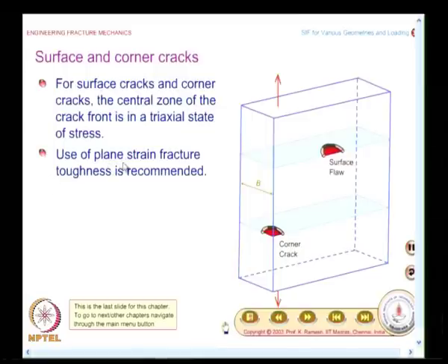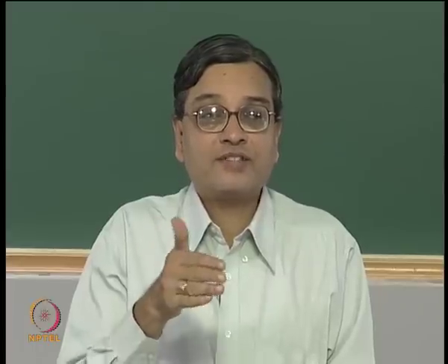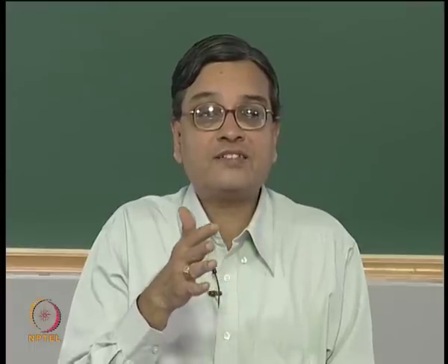And when you have to use plane strain fracture toughness, you have to recognize that surface flaws are always dangerous, because you are always comparing the stress intensity factor of a surface flaw with a through the thickness edge crack. But for an edge crack in a reasonably thin plate you may use a plane stress fracture toughness, but if you have a surface crack then you have to use a plane strain fracture toughness.